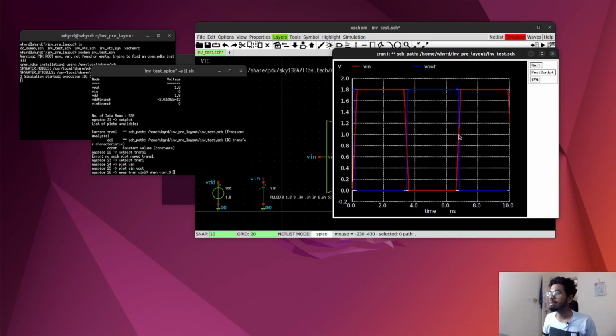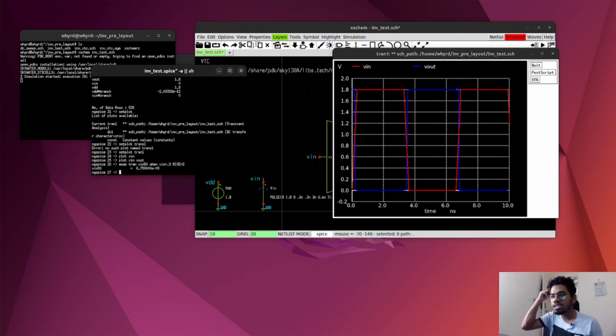So which time do we need to define, right? And for that we have a variable, and that is fall or rise, we can define. I won't be considering the first one because the first one mostly has junk value, so we will take the second one. But I want to calculate the lower side, when my input is going from high to low, so our input is going down and then up, rise, and it is rising for the second time, first time here, second time. So here I'll write rise equal to 2. I think everything's perfect. And see, this is your VIN.